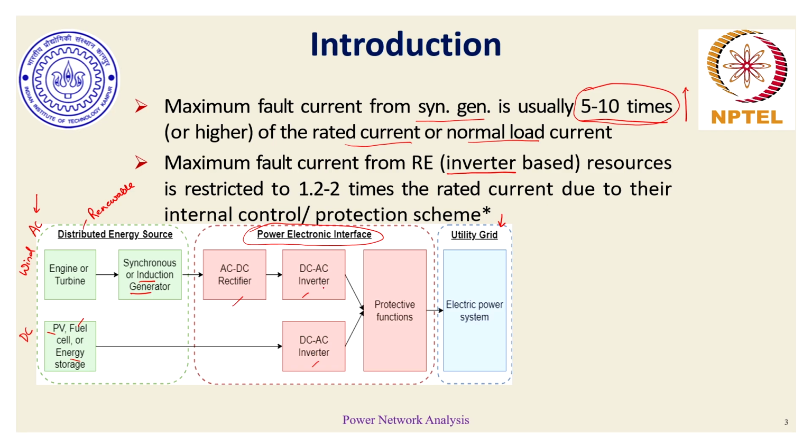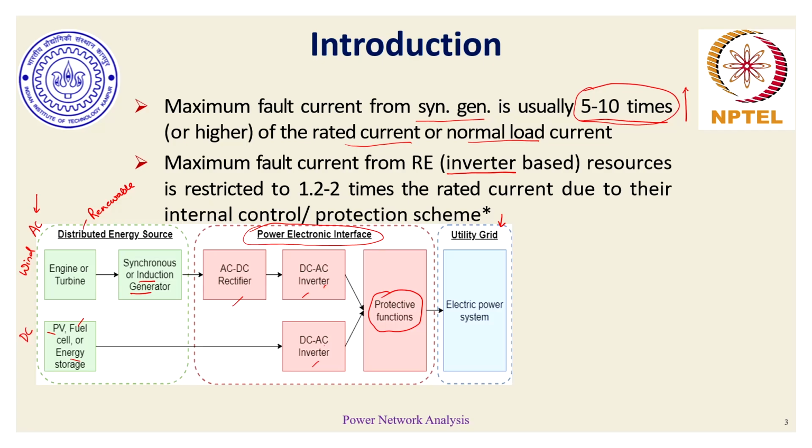And these rectifiers and inverters inherently have certain protective functions. Specifically, the switches used in these devices to regulate the voltage level or the generation frequency inherently have an overcurrent rating capacity philosophy, which entails that if some fault occurs on the generation side or on the grid side, then these inverters and rectifiers will stop operating.